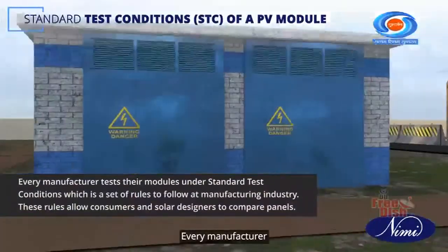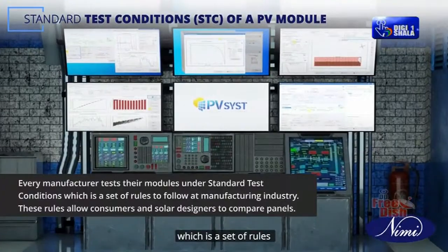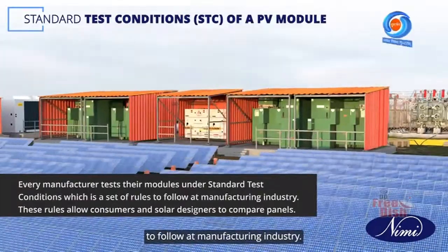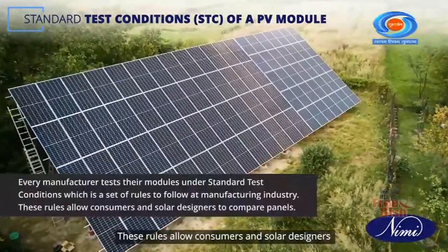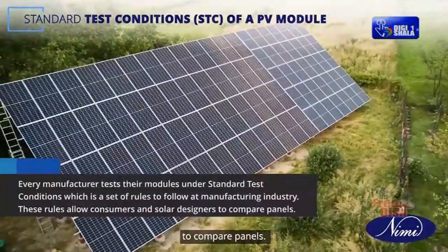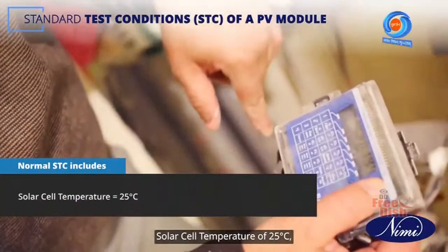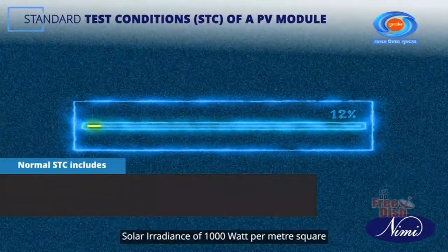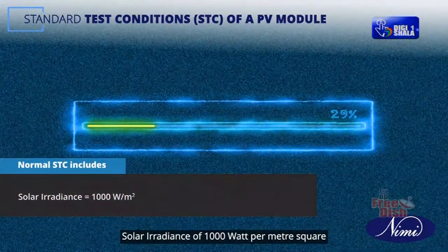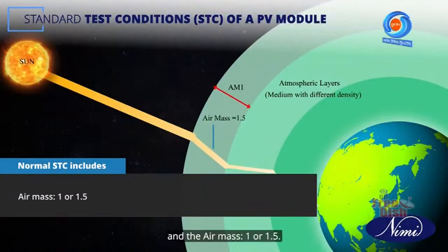Every manufacturer tests their modules under standard test conditions, which is a set of rules to follow at the manufacturing industry. These rules allow consumers and solar designers to compare panels. Normal STC includes a solar cell temperature of 25 degrees Celsius, solar irradiance of 1000 watts per square meter, and the air mass 1 or 1.5.